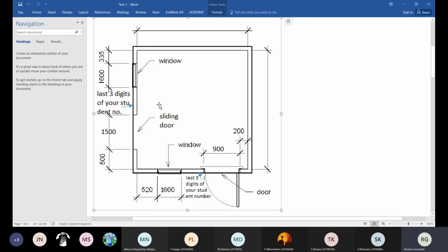You'll take away all of those from the area, and the total area that you got would have been your area of brickwork excluding your openings, right? And then all you had to do was multiply that by 55 bricks per square meter, and that would have given you the brickwork. But unfortunately, I can't do the thing, because remember, each one of you had different answers. That's why I'm explaining the methodology, and you can always go through it if you didn't do it that way, right?